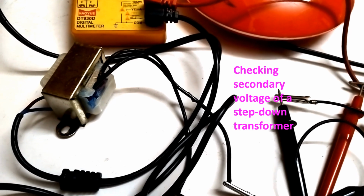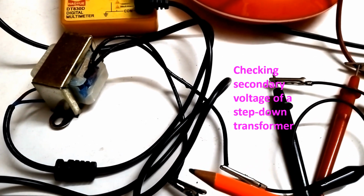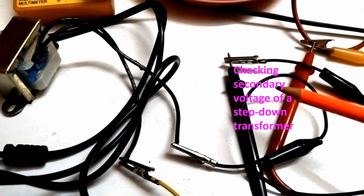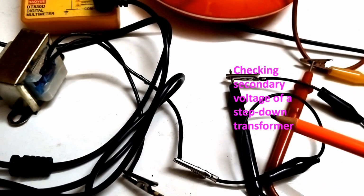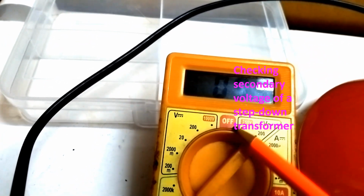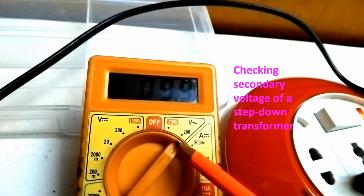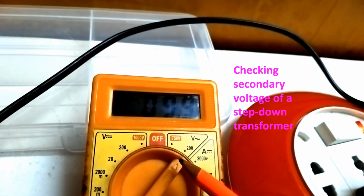Now I am measuring the secondary voltage. You can see that a pair of crocodile clips have been used to connect the secondary winding output to the multimeter, a digital multimeter. Earlier I had measured in the setting up to 750 volts, because the line voltage is higher. Now I have changed it to the 200 volt maximum setting, because I know that the step-down voltage will be lower.